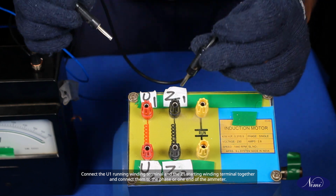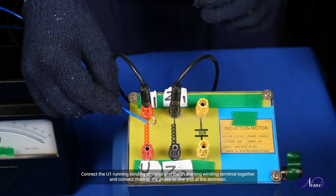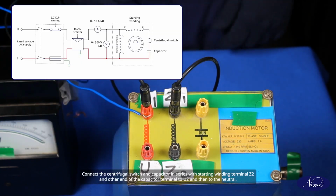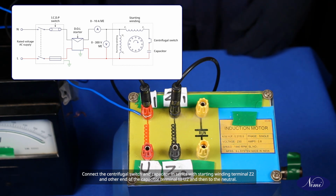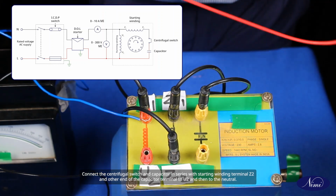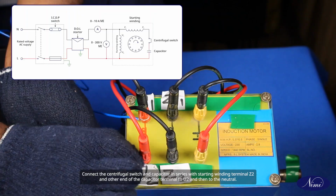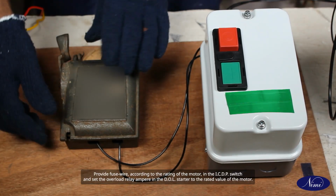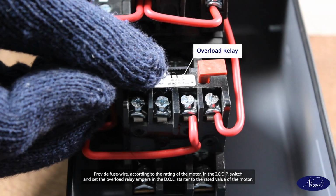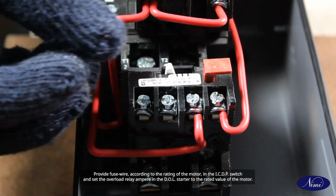Connect the U1 running winding terminal and the Z1 starting winding terminal together and connect them to the phase or one end of the ammeter. Connect the centrifugal switch and capacitor in series with starting winding terminal Z2 and other end of the capacitor terminal to U2 and then to the neutral. Provide fuse wire according to the rating of the motor in the ICDP switch and set the overload relay ampere in the DOL starter to the rated value of the motor.